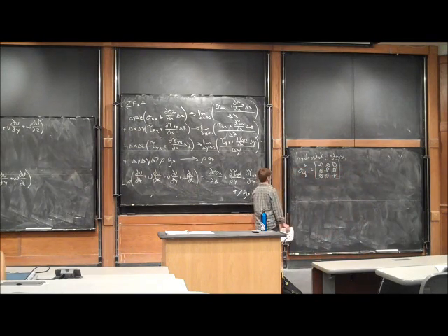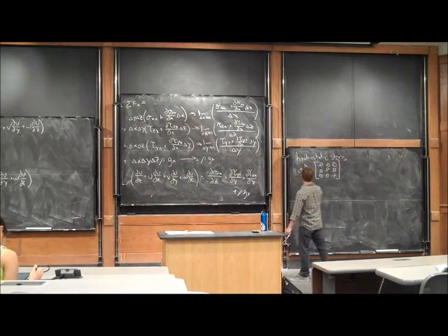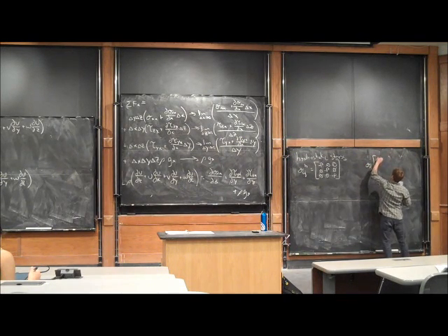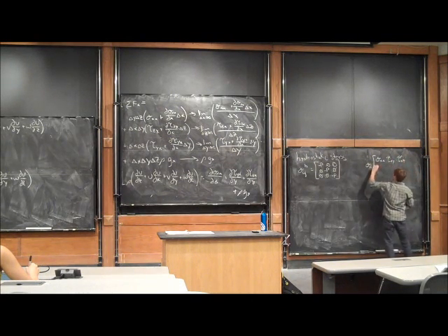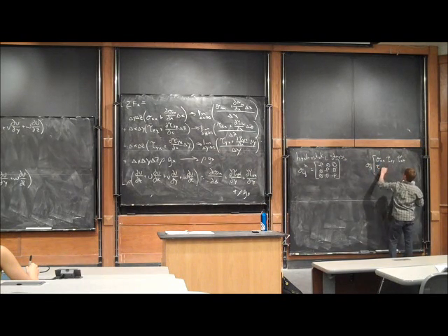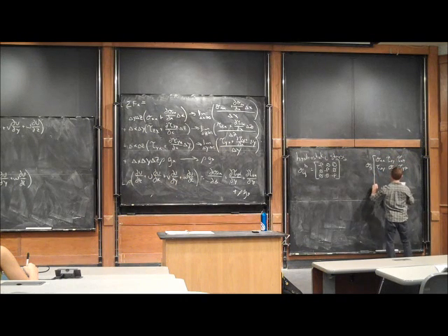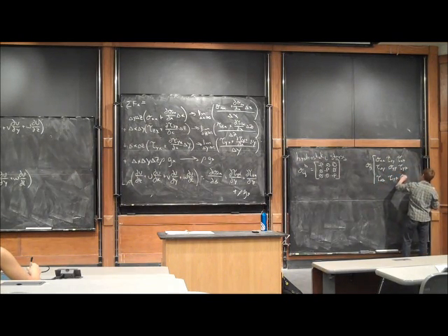Just like we had the nine stress elements acting on the fluid volume before, we can define any stress state sigma ij as sigma xx, tau xy, tau xz; tau xy, sigma yy, tau yz; and tau xz, tau yz, sigma zz.